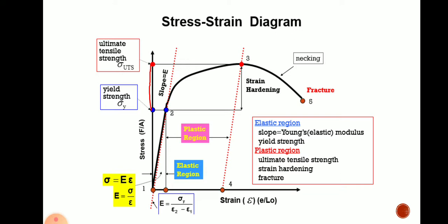Beyond this, without application of stress, there will be deformation, or a change in length of the component. From 3 to 5, there will be necking of that component. Necking means a sudden change in the dimension, and from point 3 to 5 there will be a continuous decrease without increasing strength in the strain. At point 5 there will be sudden breaking of that component.